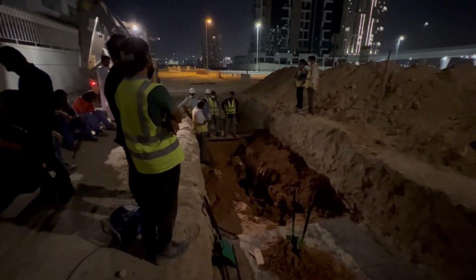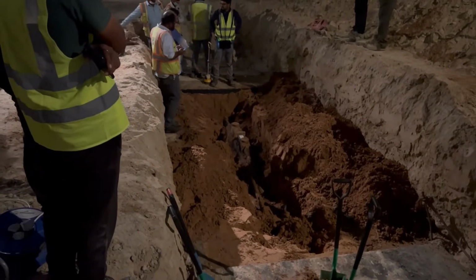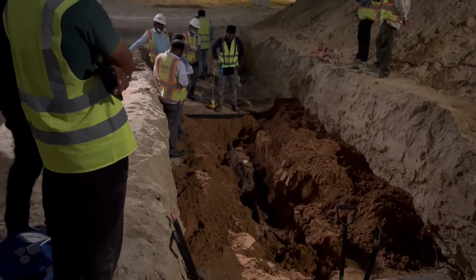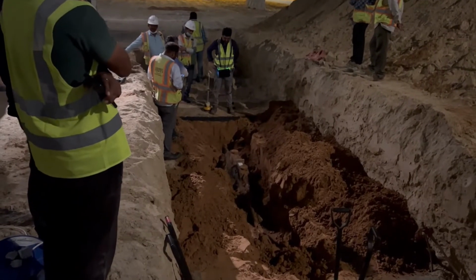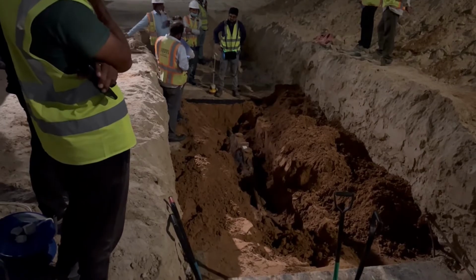Successful cable fault location at 132 kV. Found at 756 meters. It's a cable joint, and the recorded sound of arcing was also identified very clearly.